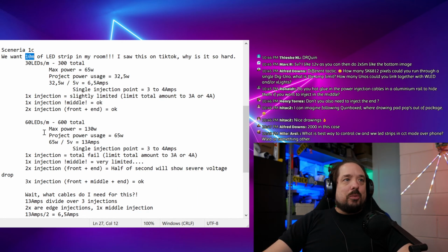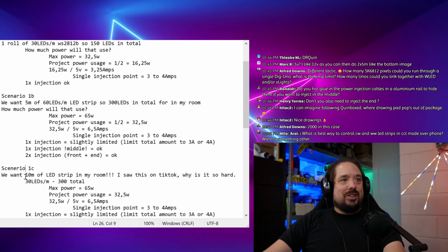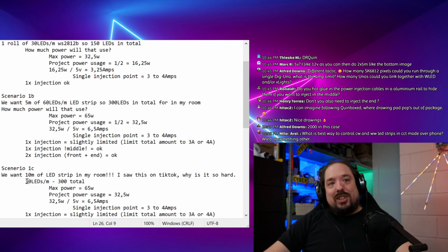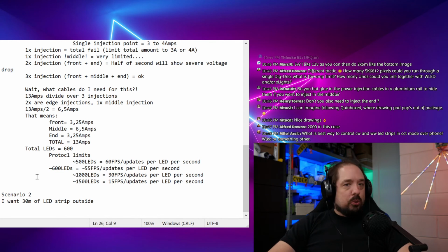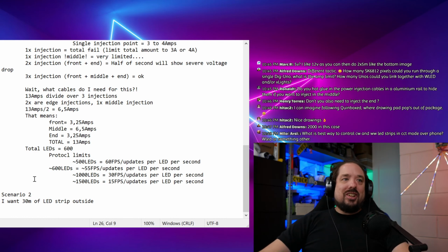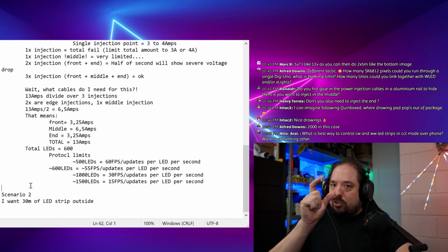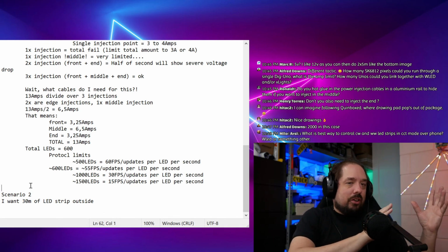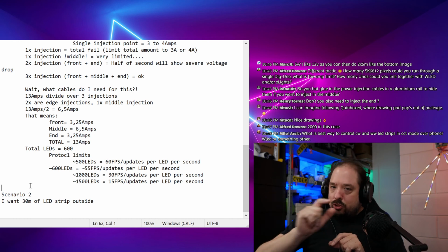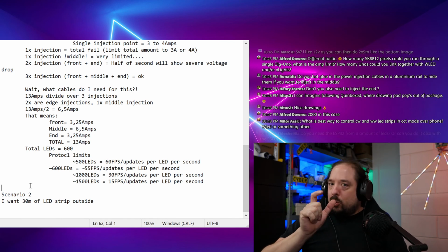That goes, scenario. What's the scenario? Okay. That makes it very interesting because, 2000 in this case? Yeah, 2000, do not run 2000 LEDs on a single output channel. It'll grind to a halt. It'll basically only do single colors. Because WLED refreshes a single color with 4 frames a second. And the effects it does much higher, but a single static color, it still sends pulses through the LED strip, but only 4 a second.